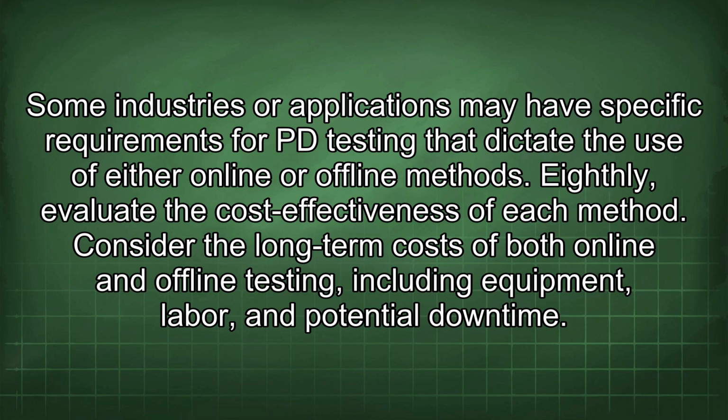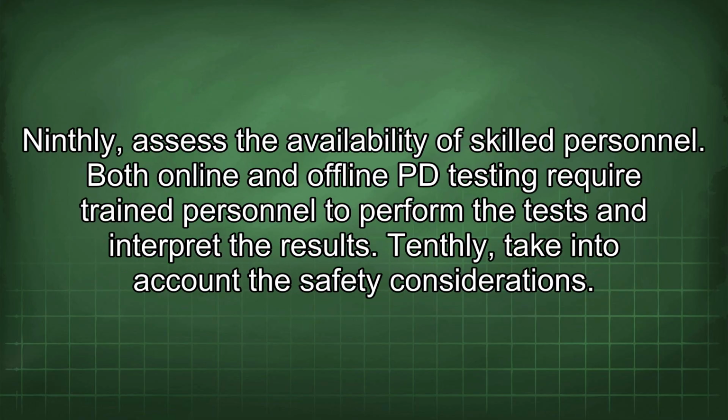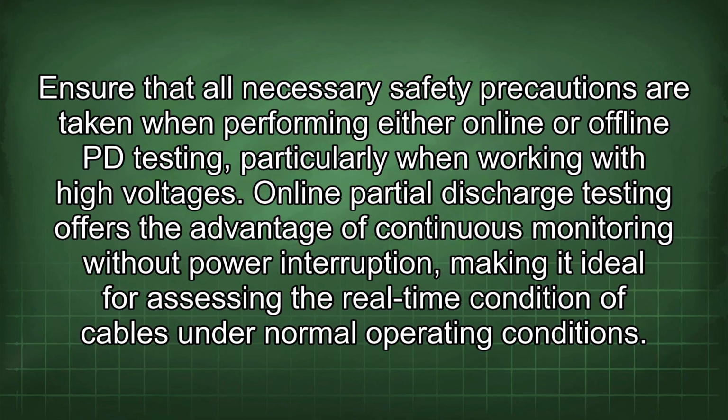Consider the long-term costs of both online and offline testing, including equipment, labor, and potential downtime. Ninthly, assess the availability of skilled personnel. Both online and offline PD testing require trained personnel to perform the tests and interpret the results. Tenthly, take into account the safety considerations. Ensure that all necessary safety precautions are taken when performing either online or offline PD testing, particularly when working with high voltages.